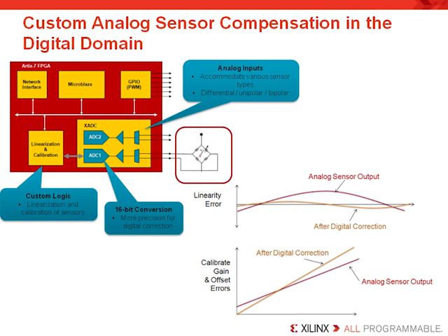Another application of the XADC core is when it is used as a general-purpose analog interface to measure currents and voltages of external sensors. Many sensor applications have a number of functions in common, so there's often the need to calibrate, i.e. remove offset and gain errors, for the analog signal processing chain and perhaps remove nonlinearity associated with the sensor itself. After the analog signals have been accurately converted by the ADCs, the logic resources in the FPGA can be used to correct or calibrate the transfer function of the sensor.